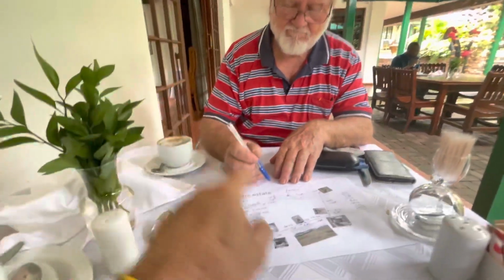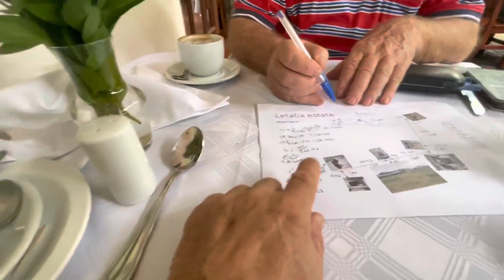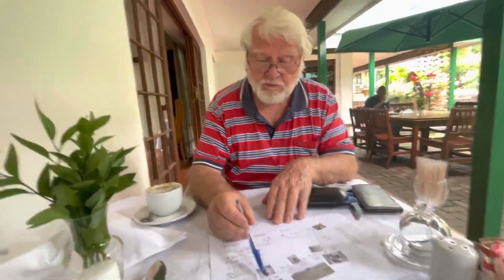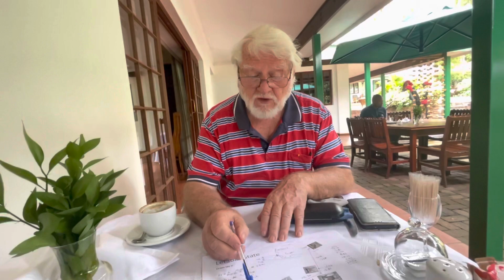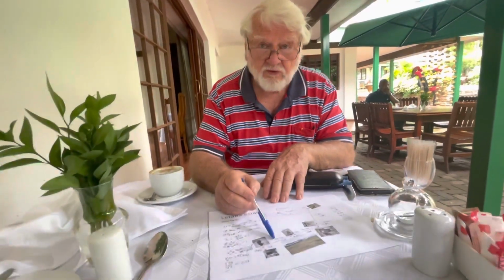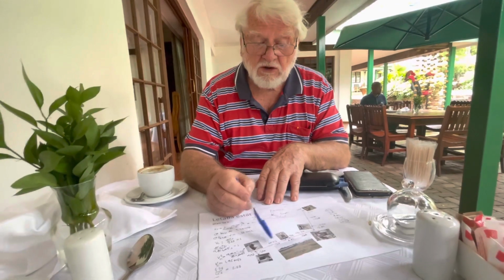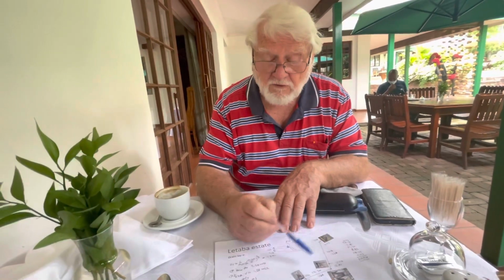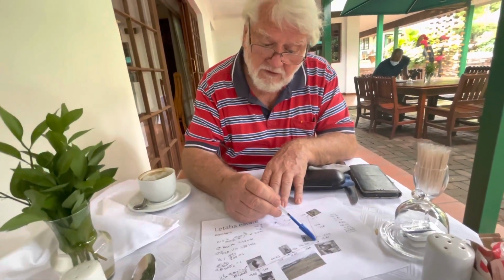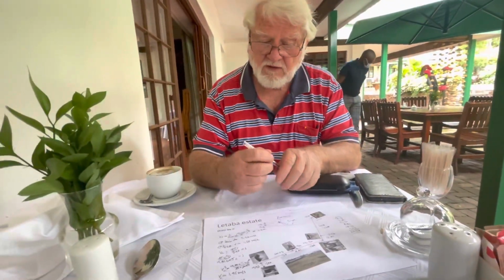And if you were designing this as a sewer pipe, would you have the same principle, whether we've got oranges transported in it? And that's why there are so many of the jobs that you've looked at where the designer has not considered the impact of changing the gradients, because you have a higher velocity here and you can, say, transport a 30 millimeter stone, and then you have a low velocity here and you can only transport a 5 millimeter stone. So if you're transporting those 30 millimeter stones down here and you get to the flatter gradient, it deposits all those stones, and then you stop them.